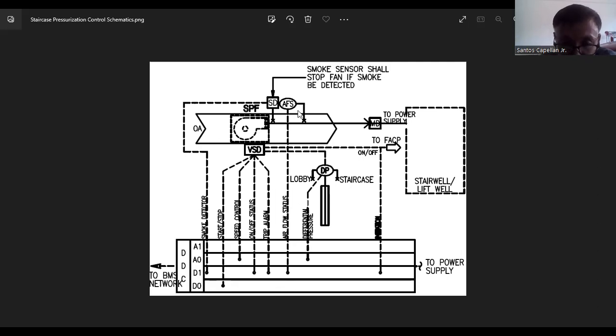Let's say basically this differential pressure switch has a differential pressure range of maybe around 200 pascal. Then there will be a set point there. Let's say you set the set point to around 80 pascal. When that set point is reached, meaning there is a differential pressure of 80 pascal between the suction and the discharge side, then the normally open contact will close. Again, it is a digital input because the value is on and off. Okay, so you are correct if you said it should go to digital input.